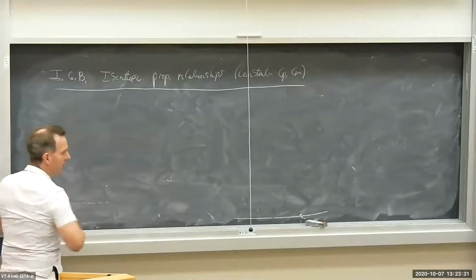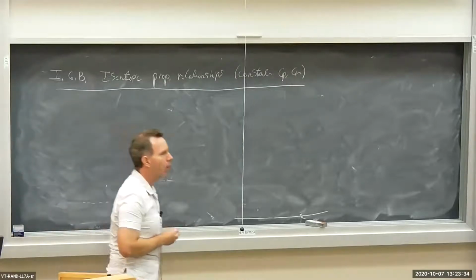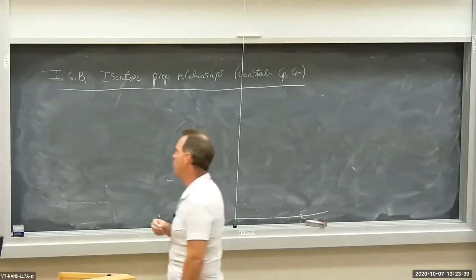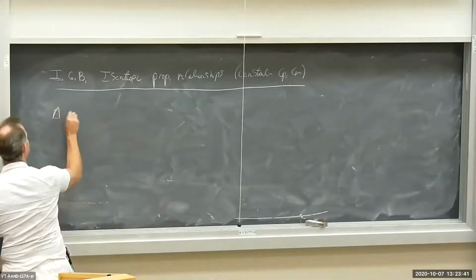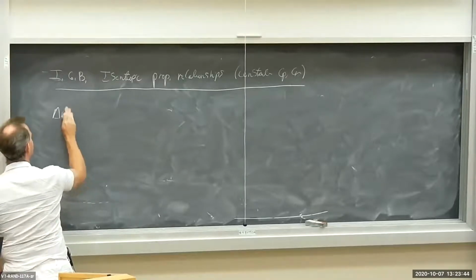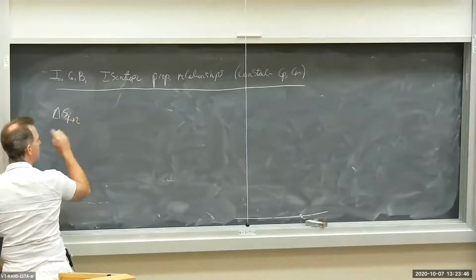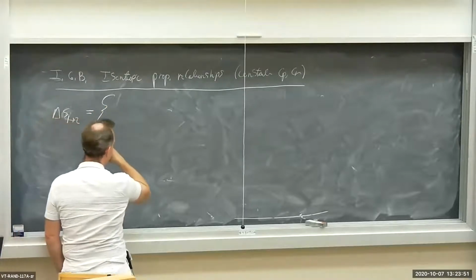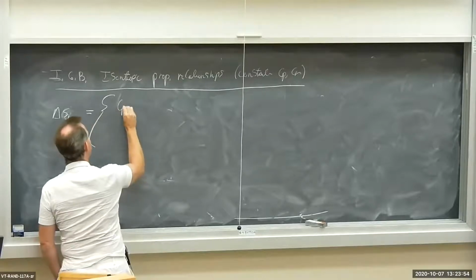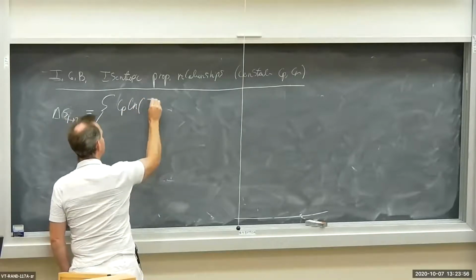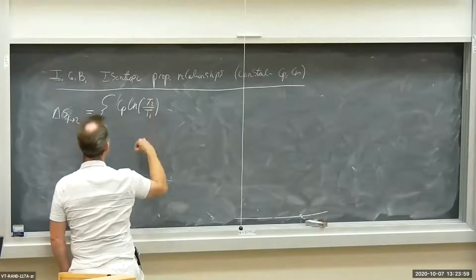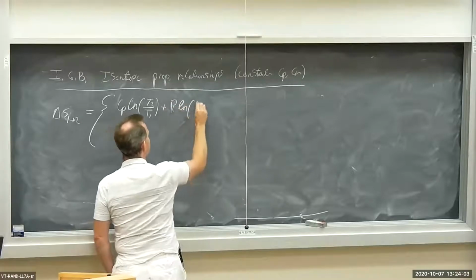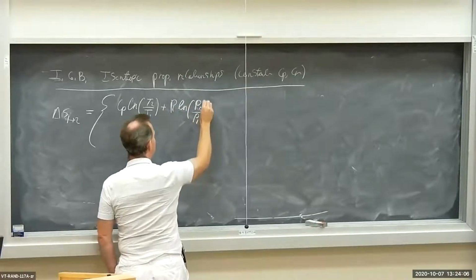Okay, so we previously had two equations that were valid for an overall process, ideal gas behavior, constant specific heats. As you recall, we had two equations. We had delta S, the change in specific entropy from state 1 to state 2, equal to, and I had two expressions. I had Cp ln T2 over T1 plus R ln P2 over P1. Okay, that was one expression.